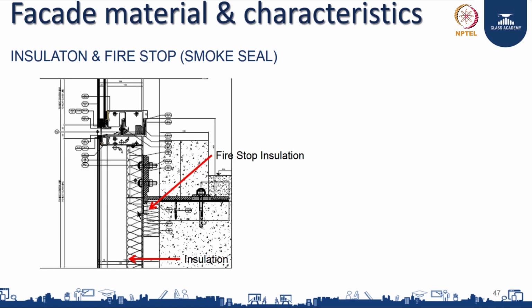You can't just simply say, okay, I want to put glass all the way. Glass breaks unless you have a fire rated glass. The normal glass will break immediately when there is fire. So it is always advisable. See, normally a fire spread takes up to 1.2 meters when it goes from the floor above to the floor below. So the common practice is to have a good spandrel zone insulated, so the fire takes time to spread to the next floor. So it gets contained.